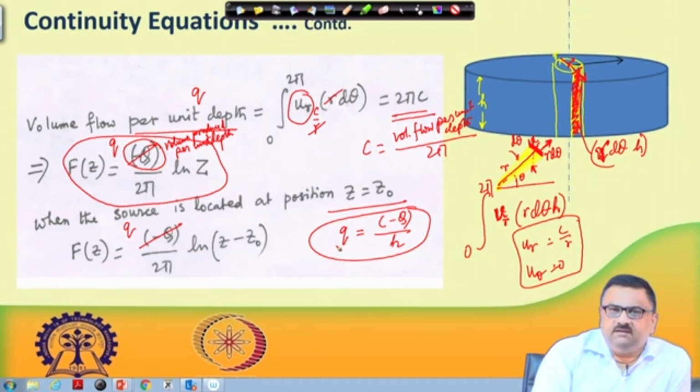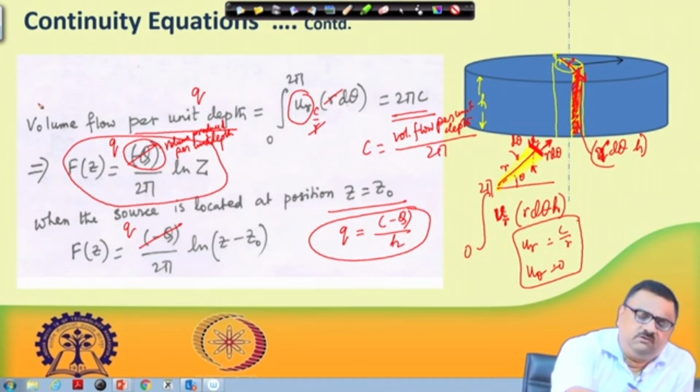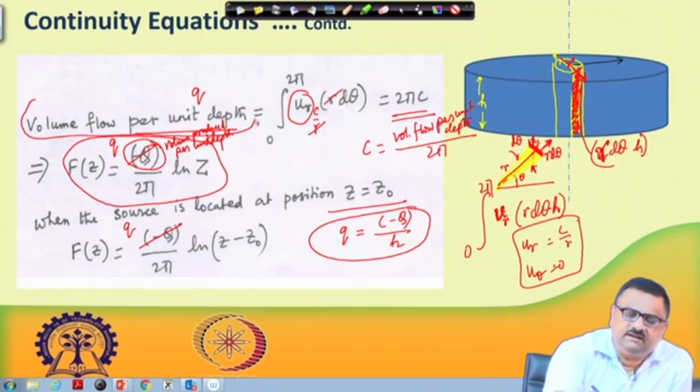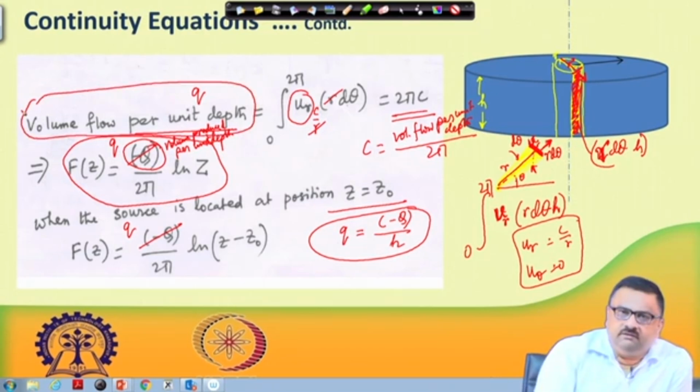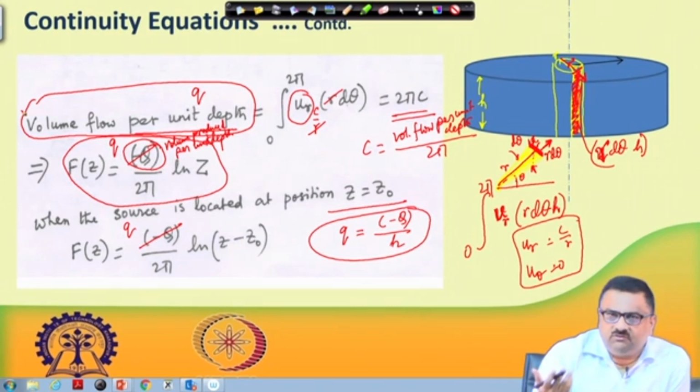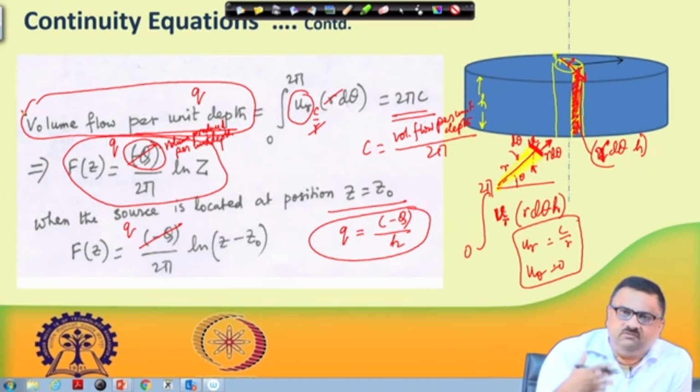My sincere suggestion here is to work with the units, because in some cases we are talking about volumetric flow, in some cases volume flow per unit depth. Actually, we got into volume flow per unit depth because it is directly linked to the stream function. In another case we are talking about volume flow rate, and in another about superficial velocity, which is volumetric flux.